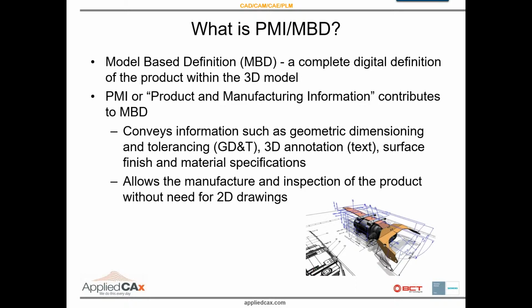If you attended my Tuesday webinar, I'll cover a couple of things just to make sure that everybody's on the same page. So, what is PMI and MBD? PMI is NX's expression of model-based definition. It's to document your model in 3D space. When your model is documented in 3D space, you can eliminate the need for a paper drawing. It doesn't necessarily mean you have to, but it is a quick and easy way to convey your design intent, and you can end up with fewer mistakes by using 3D model-based definition.